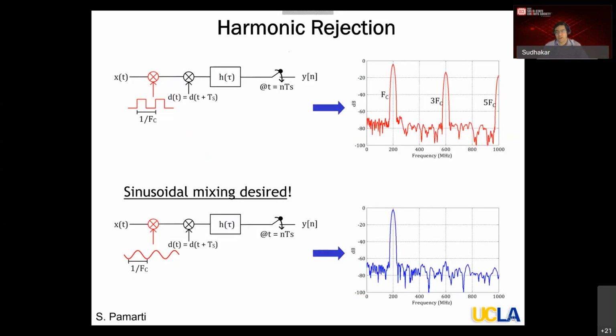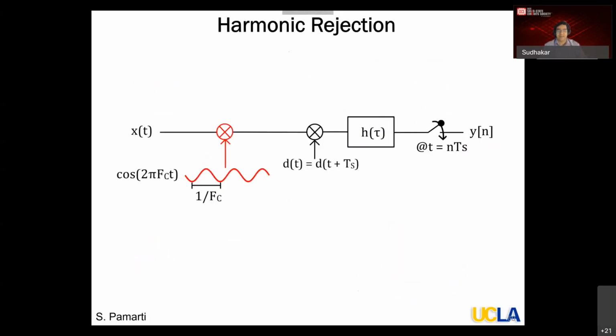And we know this thing. Harmonic mixers essentially try to do the same thing. They have multiple LOs, different LOs of the same frequency but multiple phases, and then we weigh them and add them. It's a standard harmonic mixer. In FA, it turns out I can do that very, very easily by simply